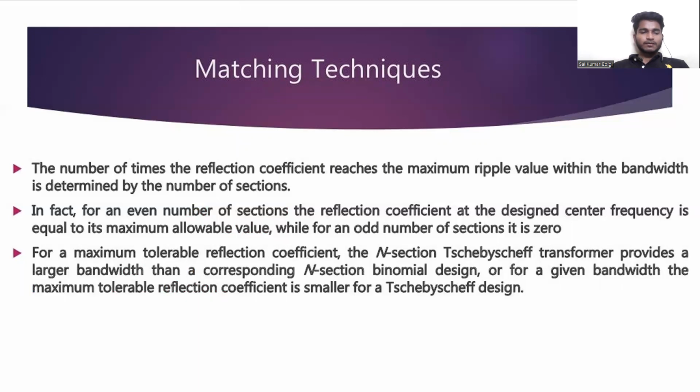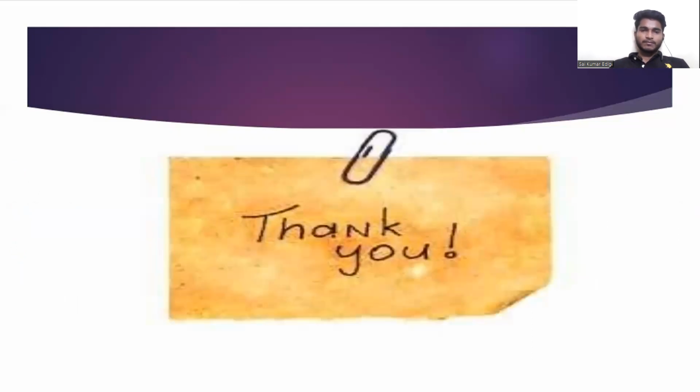Next, for a maximum tolerable reflection coefficient, the n-section Chebyshev transformer provides a larger bandwidth than a corresponding n-section binomial design. Or for a given bandwidth, the maximum tolerable reflection coefficient is smaller for a Chebyshev design.